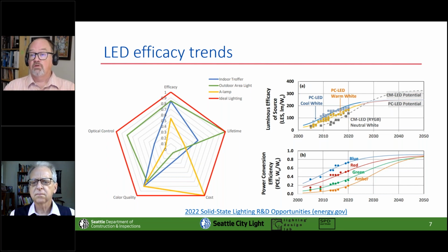And what we're finding is that LEDs, of course, as we understand, become more efficacious over time. At a certain point, we're going to run out of that. But the good news is that lighting is now really using so little energy in the buildings. And this is giving us that idea of some of the opportunities. So then, next slide, Duane. Before we go, is that accurate on the upper right there, that right now warm white LEDs should be crossing into the 200 lumens per watt?